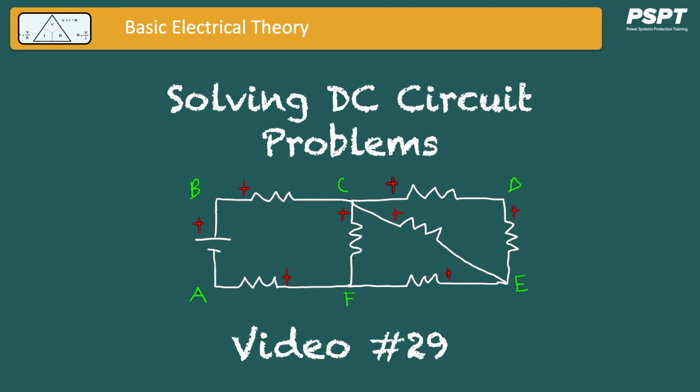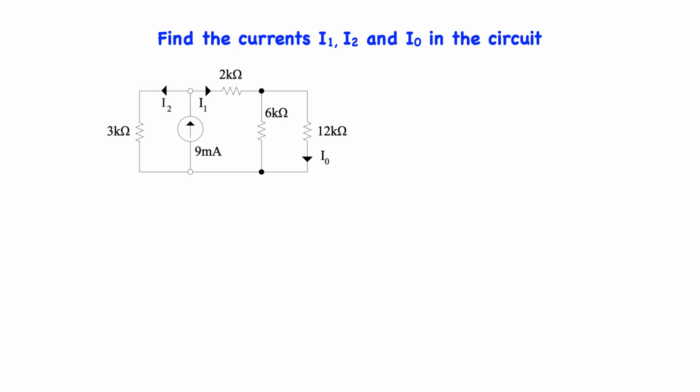Video number 29. Solving a DC circuit problem. In this circuit we are tasked with finding the currents I1, I2, and I0. If we combine the paralleled 6 and 12 k ohm resistors, we get 4 k ohms, and the network is reduced to look like this.